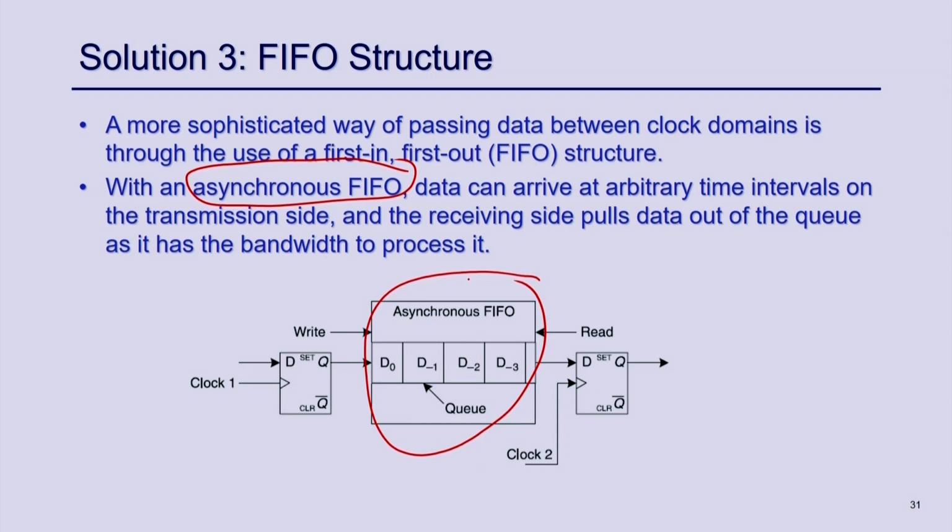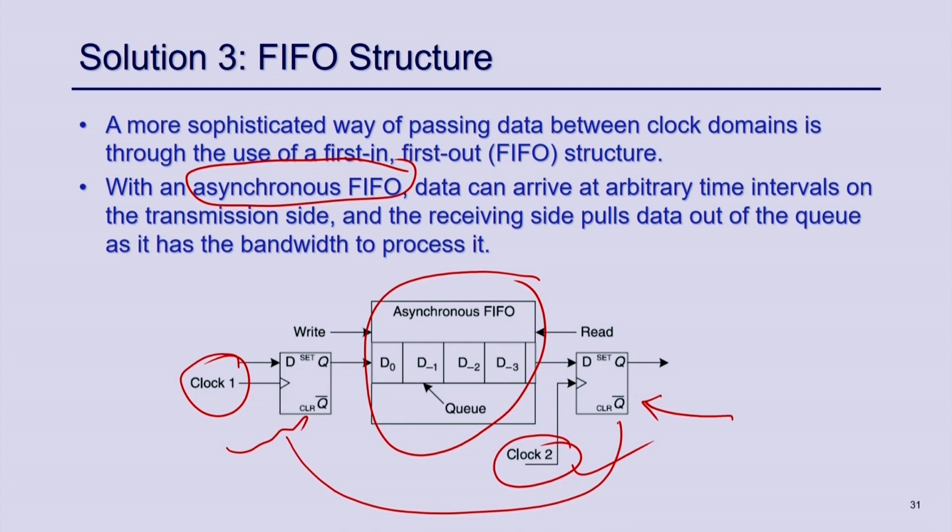If you reflect the same scenario here, this is the customer side, and they are writing this data, and this is the biller side who actually accesses this data and processes the data one by one. So, the way it is happening here is that whatever data is coming will keep being written into this particular asynchronous FIFO in clock 1, and this will be reading this data at the speed of clock 2, right. And there is no problem, because there is no direct communication between these two.